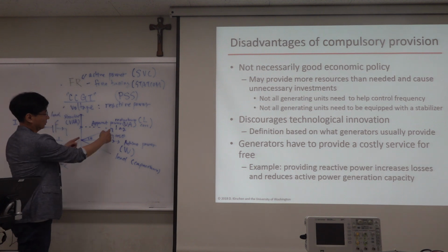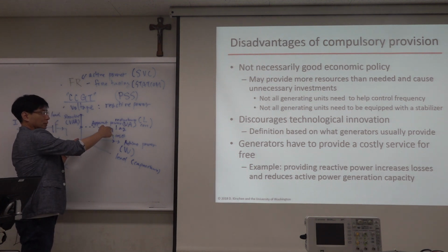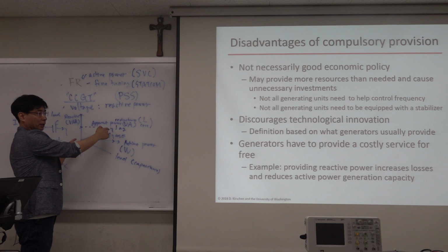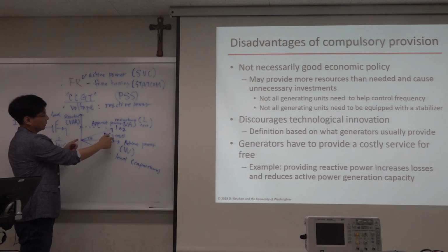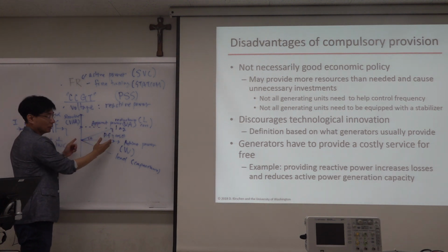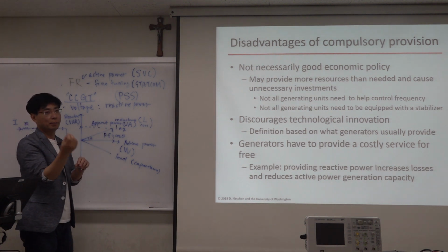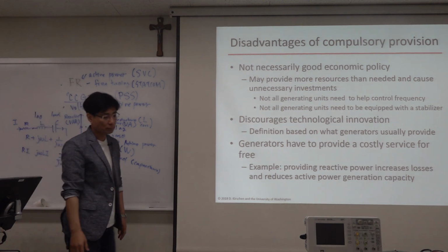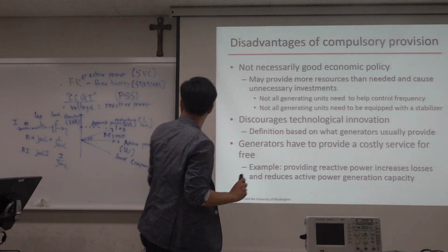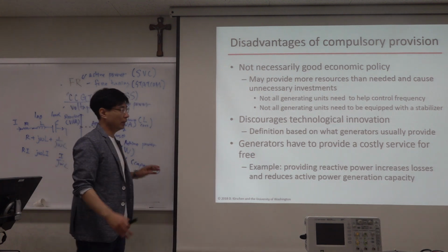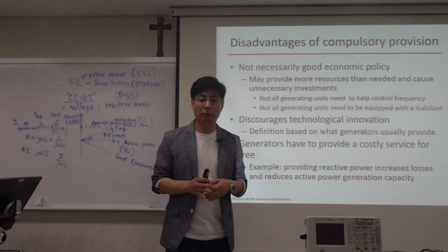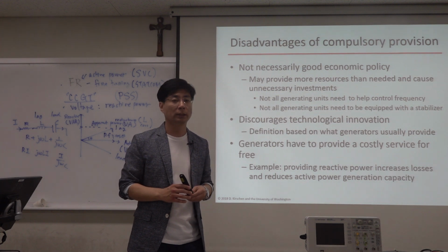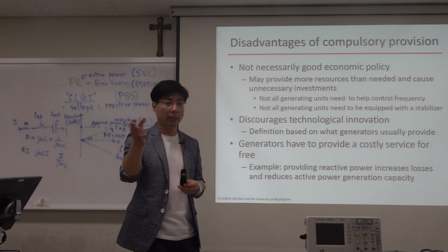Yeah, obvious, no. This magnitude is the same all the time. So providing reactive power means that the cosine theta times this is reduced, right? So to provide the maximum active power, the power factor should be 1, right? Yeah, in this diagram, that is obvious, but intuitively, how can you say that? Think about it.